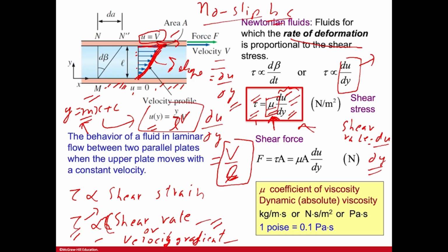As a result, the stress is going to be higher, because your viscosity increases. Now if your stress is higher, naturally your force is going to be higher. Your stress and force are related by just the surface area. So if your area is constant, then stress times area is force. So if your stress is higher, force is higher. So you can see how this relationship comes into play. This relationship is actually very important when it comes to fluid mechanics. So let me just highlight which relationship I'm talking about. This one in red.